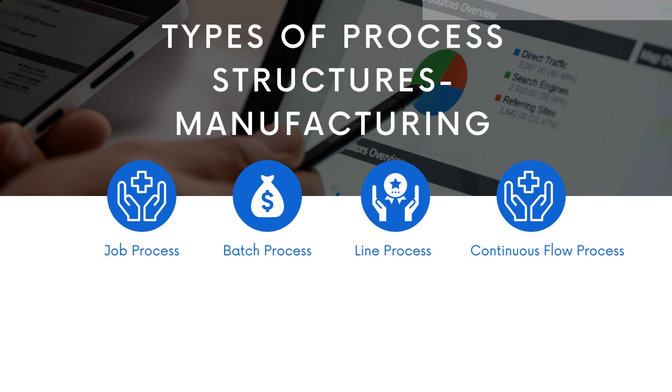Batch process is the standardized job shop process, which is pretty commonly used, especially within the manufacturing industry. Batch process makes use of either small quantities or large quantities or batches, or whatever you want to call it. Every batch produced by the process is completed in its entirety before the production for the next batch commences. So you're producing it in batches as and when you get those specific orders.